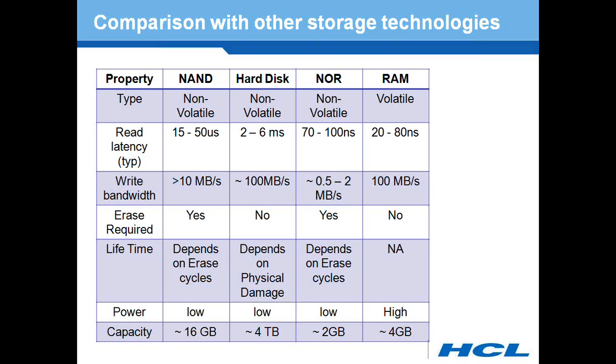The next property is the erase requirement. When you reprogram a page, NAND must be erased before writing any data into a NAND flash page. So an erase operation is required for NAND as well as NOR flash, whereas there is no such requirement for hard disk and RAM.